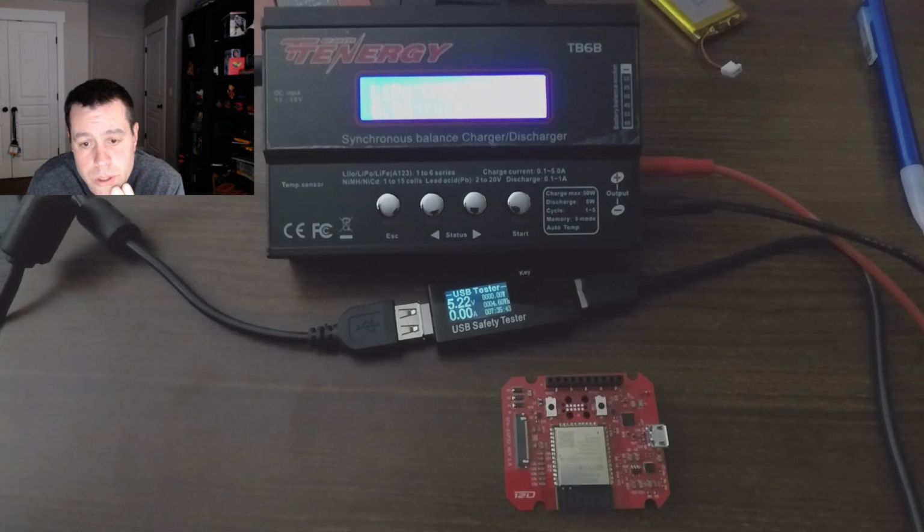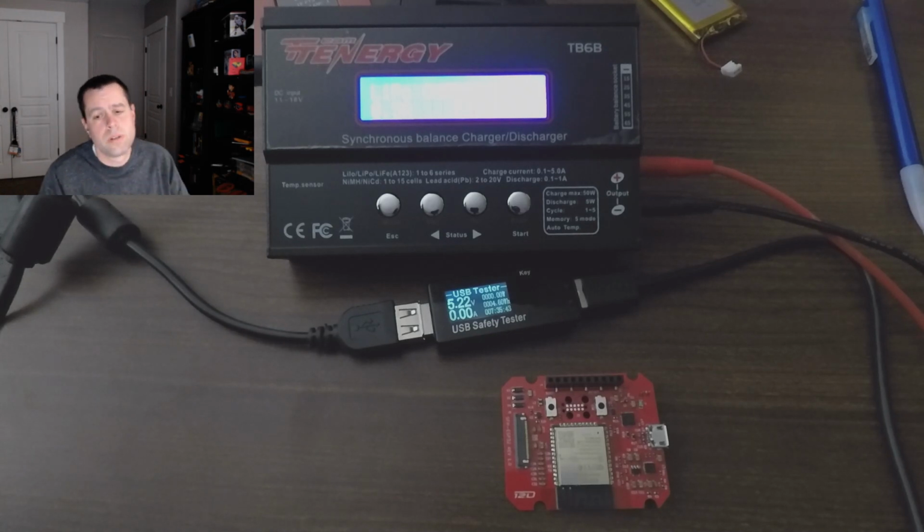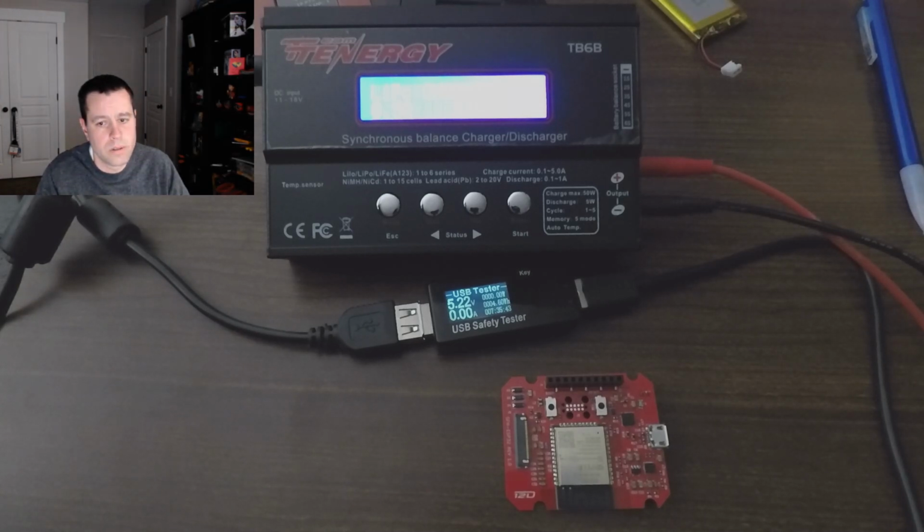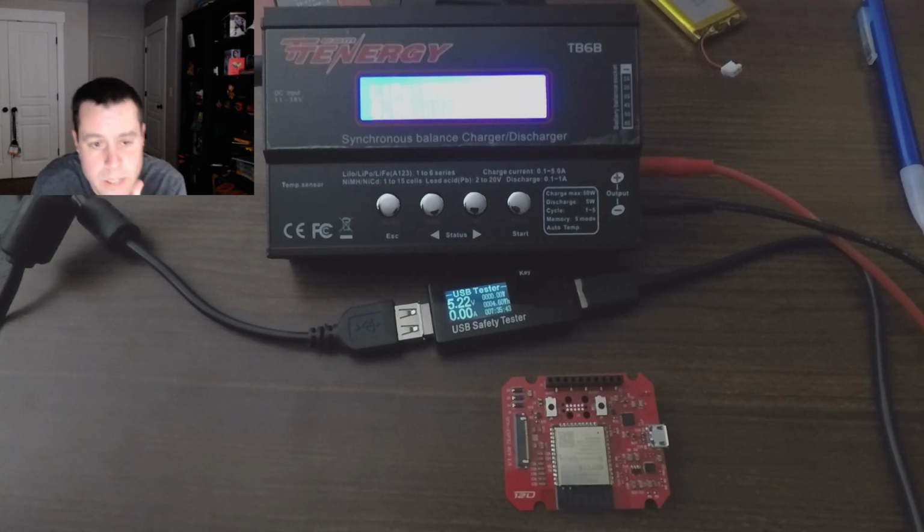And when they're charging, they're pulled down, but that shouldn't matter. V over R, 3.3 divided by 100K is tiny. I don't think we're losing it there. Divided by 100,000, we're talking microamps of bleeding current there. So it's not that.